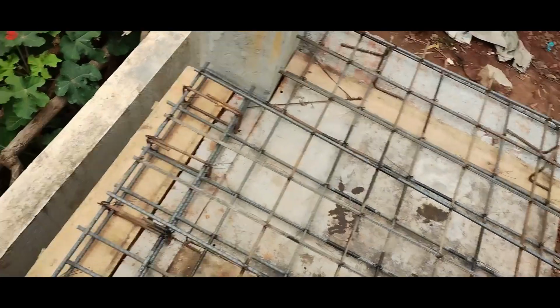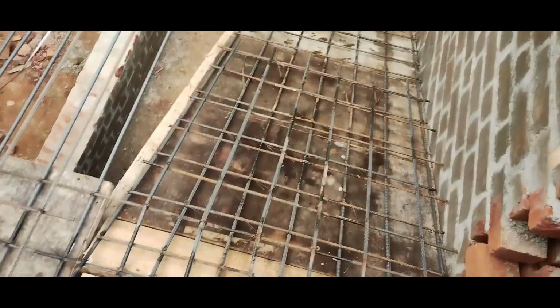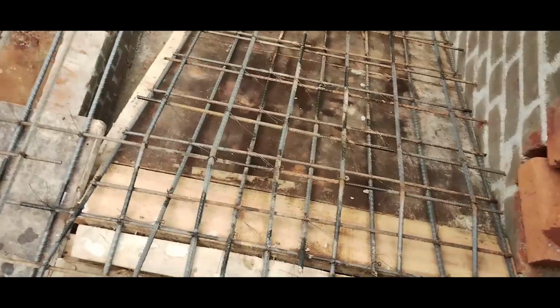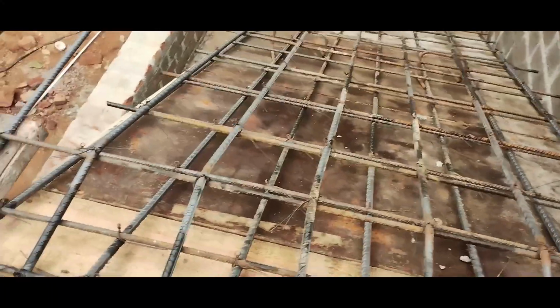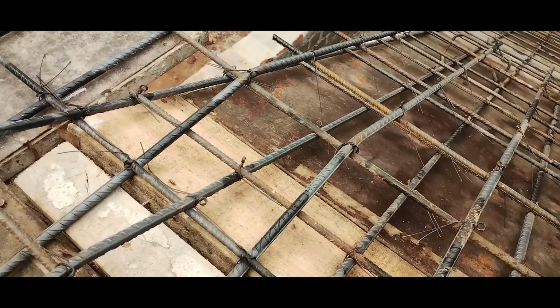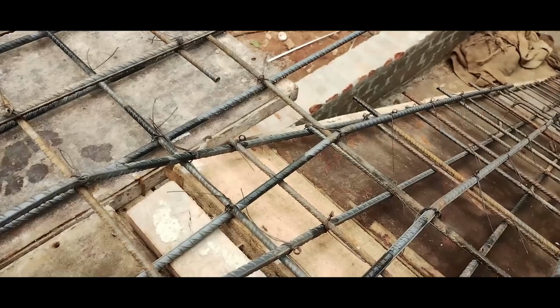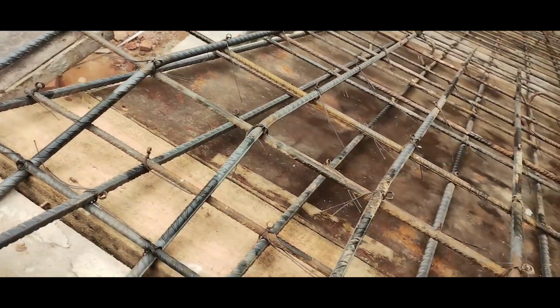All right, so you can see here, this is one end of the staircase. The other end of the staircase is over there. The other part that I wanted you to see was this part. Let me just sit down here and show it to you. You can see alternately the bars are cranked. Whatever the bottom reinforcement is, it comes and gets bent to the top part, and whatever the top part is, it gets bent to the bottom part.